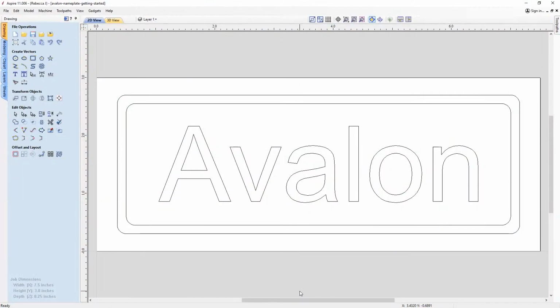Okay, so guides are a very useful way to help lay out designs in the 2D view. To get a guide, you simply pull on the ruler and you can drag that down or up, and you can go onto the side here and drag that across. You can see that those guides are just coming into place, and I can snap them to other vectors if I wanted to, like so.